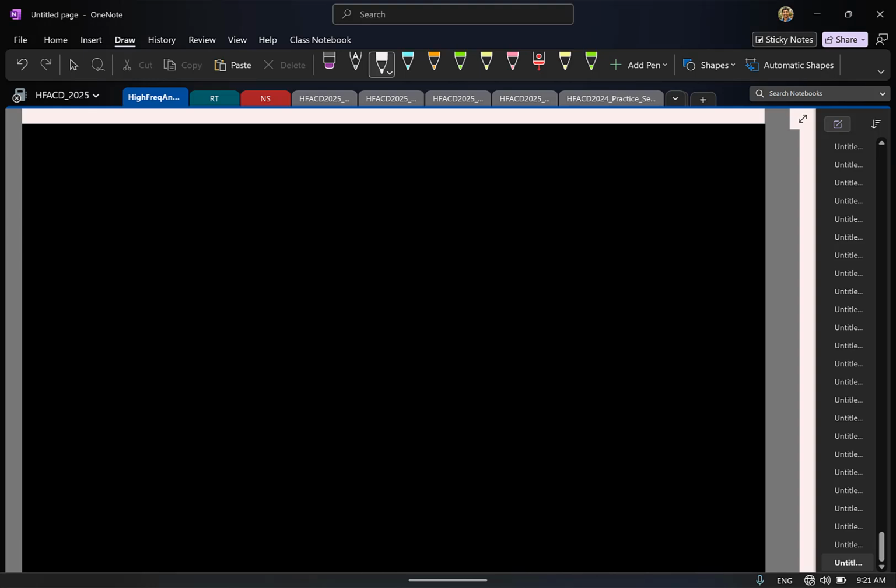Common gate means the gate is incrementally short, I apply the input here, and I take the output from the drain. So I'll have RS and Vin here. As usual, I am computing the noise, so I'll make sure Vin is 0. So this is short.